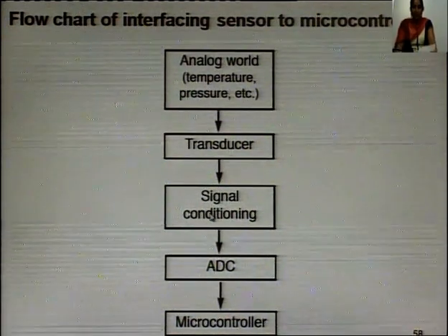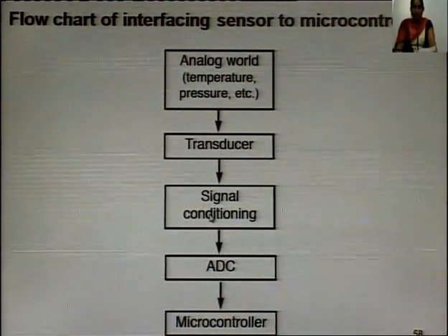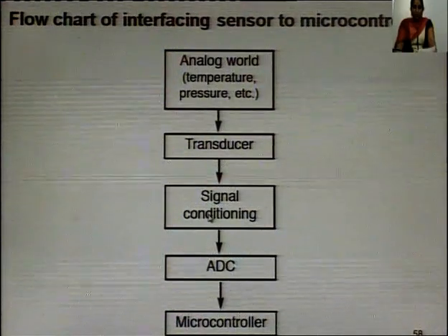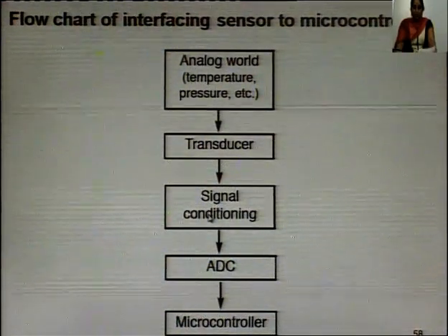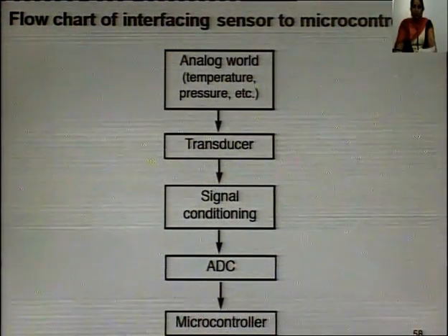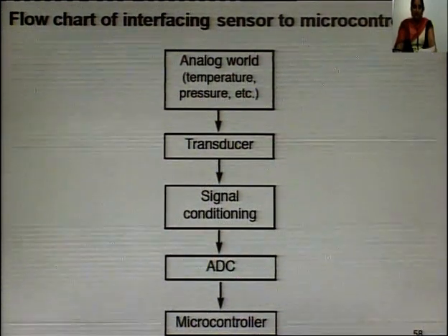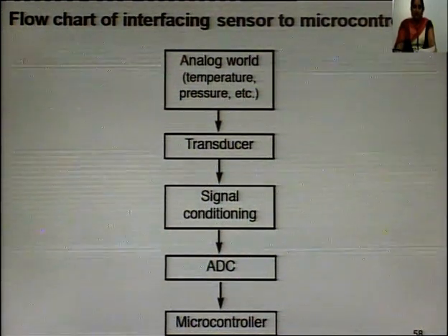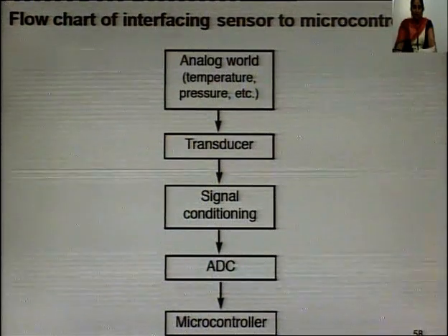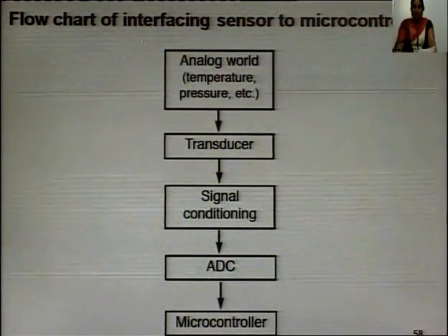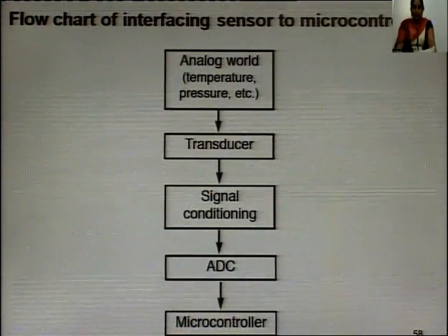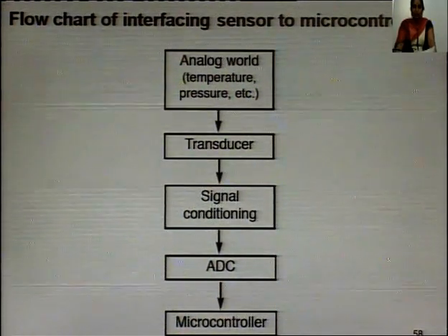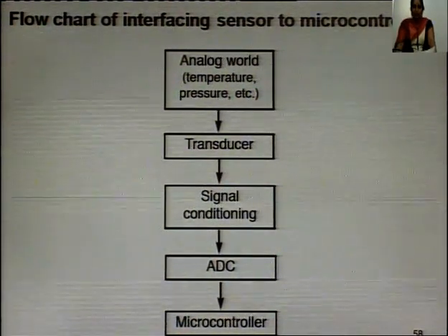Signal conditioning is widely used in the world of data acquisition. The most common transducers produce an output in the form of voltage, current, charge, capacitance, resistance, etc. However, we need to convert these signals to voltage in order to send them as input to the analog to digital converter.